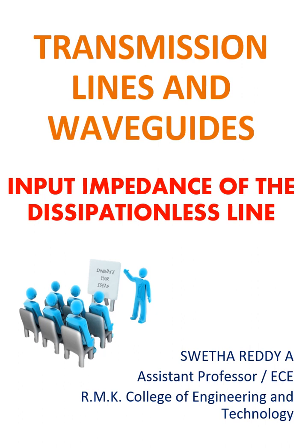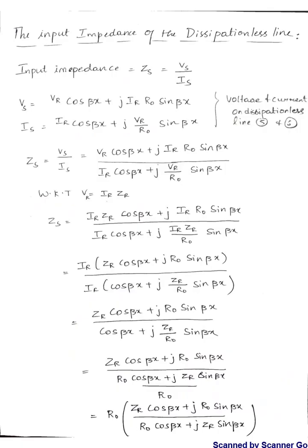So today in Transmission Lines and Waveguides, we are going to see a topic called Input Impedance of the Dissipationless Line. So let's move into the topic. Coming to input impedance of the dissipationless line, normally the input impedance formula is Zs is equal to Vs by Is. And these two equations, Vs and Is, are from the previous video, where we saw the voltage and current on the dissipationless line. In that topic I derived the fifth and sixth equation.